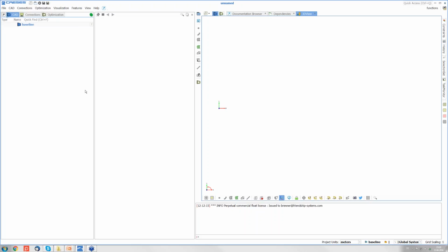And what we are using in CAESES to describe this parametrized cross-section through the surface is the so-called feature definition. The feature definition is something that can basically be compared a little bit to a script. So you have certain input, in this case the parameters that describe the cross-section, and then you use this input to produce a certain geometry, and the geometry objects that you're creating within the script are the output of the feature.